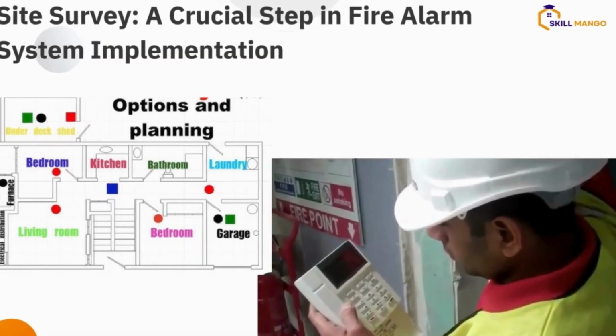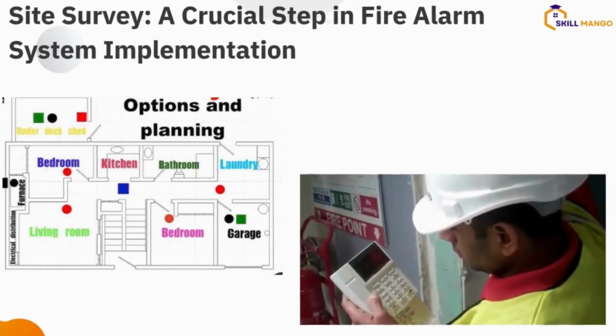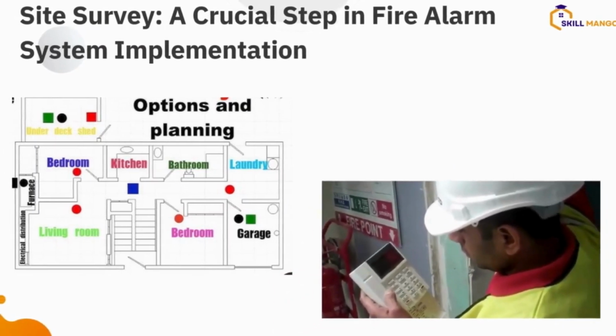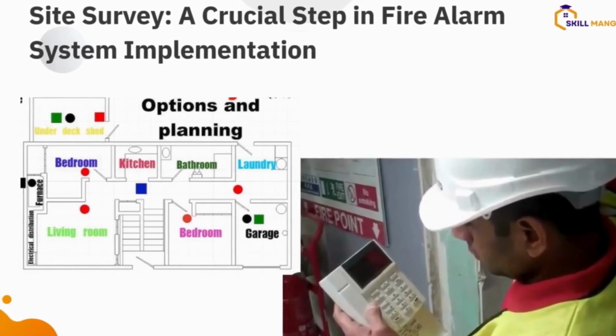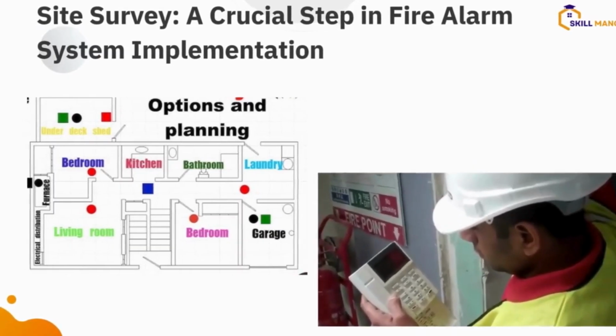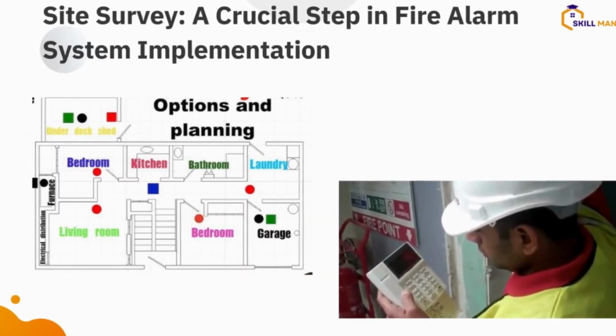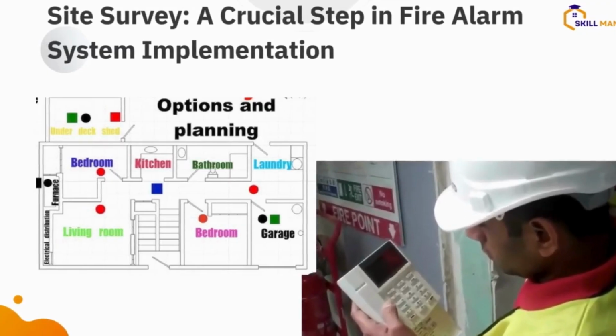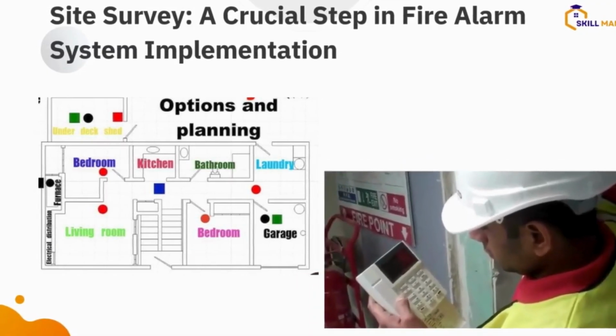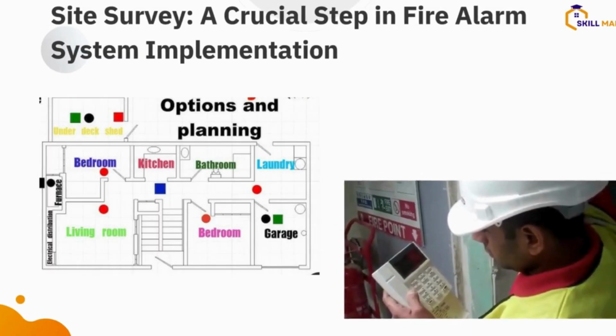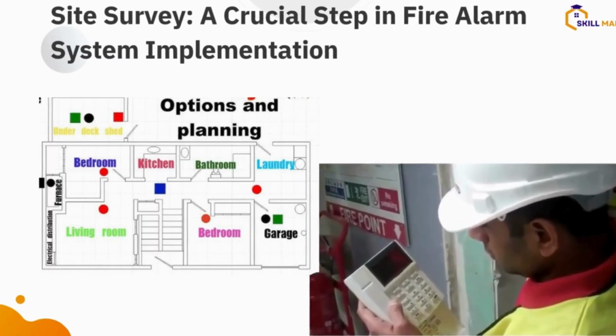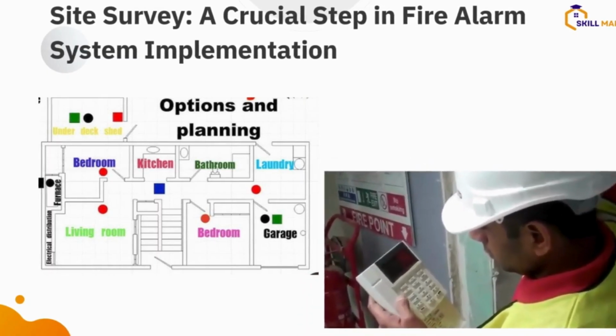So it's advisable you interact, engage, or collaborate with the electrician on site, or if possible, bring your own electrician to carry out the route planning with you. You just tell him, okay, I want one smoke detector in this center. I want the break glass at the corridor to link to this smoke detector, to link to this break glass at the other corridor.